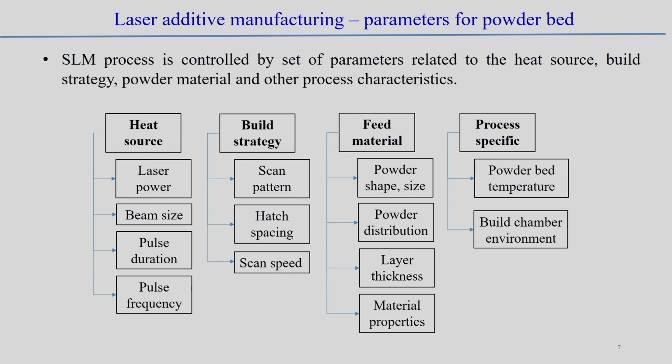So, what is the laser power, what could be the beam size, what should be the pulse conditions, the pulse duration, the pulse frequency, all the parameters associated with the heat source. Apart from this, then the build strategy. Build strategy means the scan path, how you decide the scan pattern.